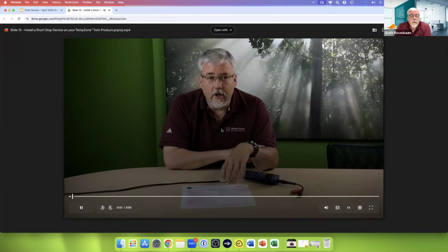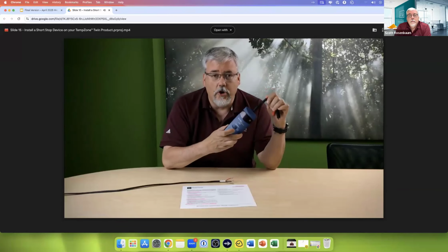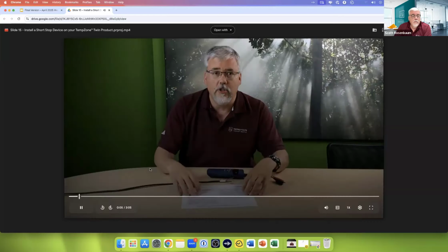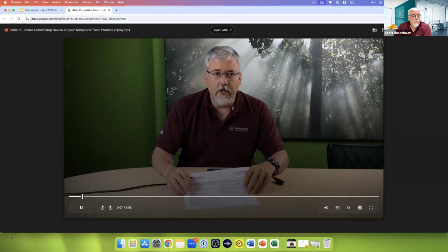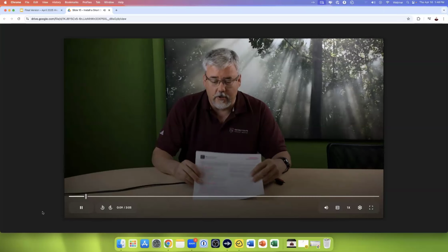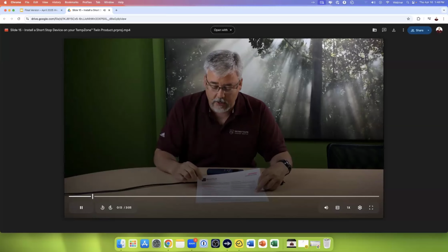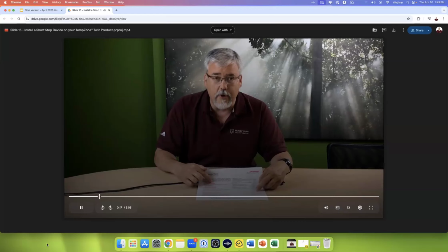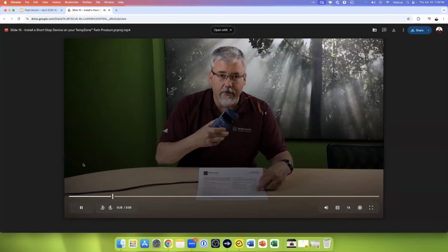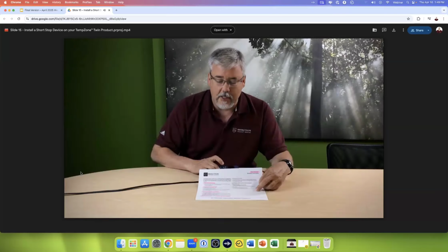Hello, today we're going to talk about using a short stop device on your WarmlyYours Temp Zone Twin product. When you get the short stop, it will come with the instructions. On the instructions, there are a few simple things to do to get your system working and the test done correctly. The first thing you need to do is find what roll you have in your floor. You'll need to refer to your original order or your installation plan for that. You'll also need to set the velocity of propagation on this unit, which is the VOP.